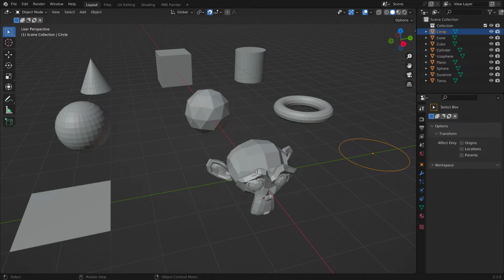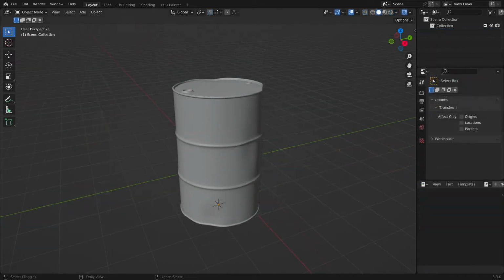To start modeling, visualize the overall shape of your model, so you can pick one of the 10 primitives to start your modeling. If the model or the part of the model you are starting with is more or less cylindrical, like an oil drum, then a cylinder would be the primitive of choice.